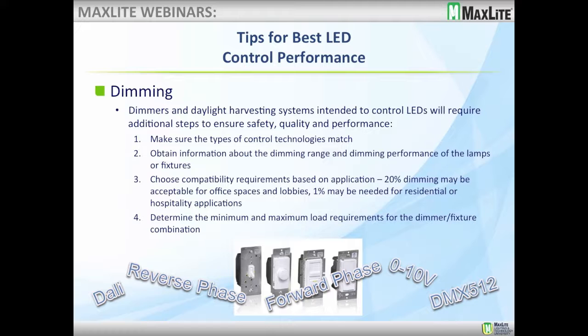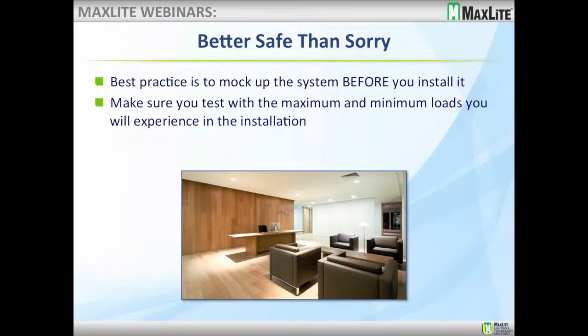Determine the minimum and maximum load requirements. And actually, what I suggest in more complex situations is to actually mock up some dimmers and fixtures together before you go ahead and do an installation. Once you have that stuff up in the wall, it's really hard to tear it out and fix it and put something back up again.